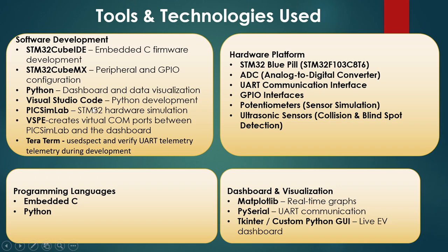Proteus Lab for STM32 hardware simulation. I also used other tools like VSPE and Teraterm. VSPE creates virtual connections between COM ports between Proteus Lab and the dashboard. Teraterm is used to verify UART telemetry during the development.